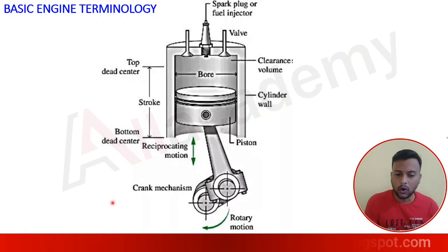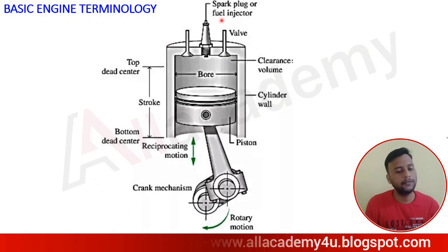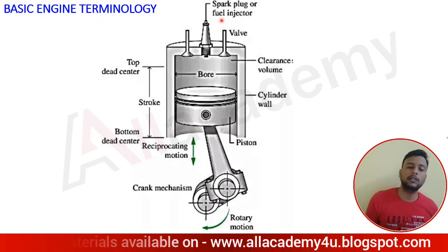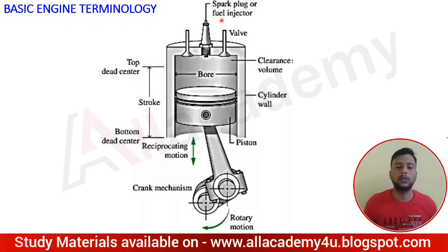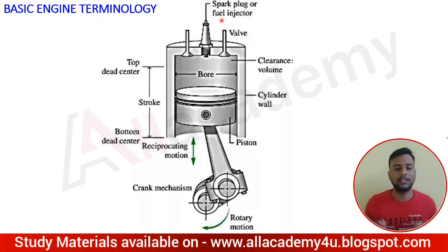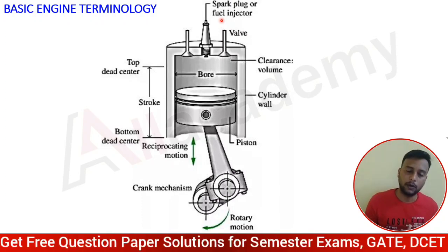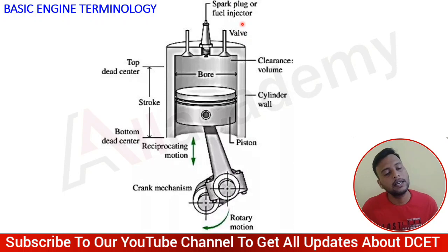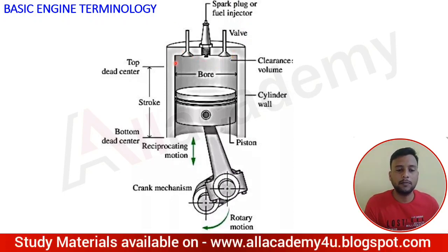Already you know about all these components. Spark plug is there, or fuel injector. What is a spark plug? It is a device that produces a spark that helps to burn the fuel. What is a fuel injector? Very important, many students make a mistake. If you ask generally where the spark plug is used, everyone says that the spark plug is used in all vehicles. No, the spark plugs are used in petrol engines and the fuel injectors are used in diesel engines. Please note that.